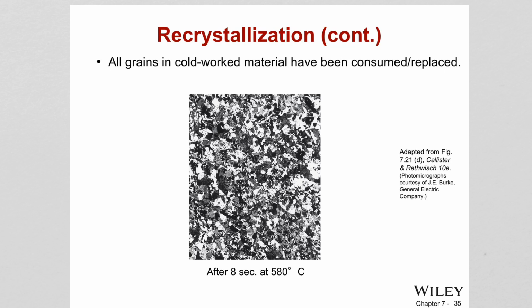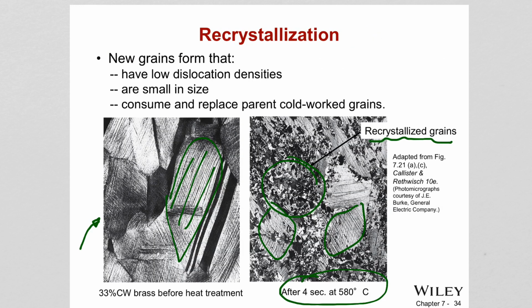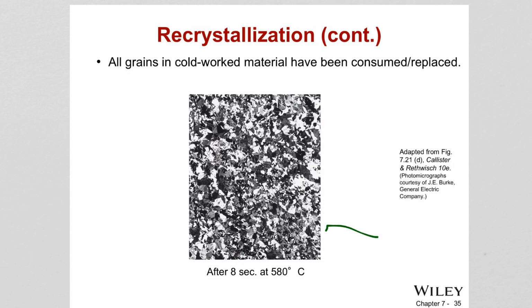Now after 4 seconds, think about just within 4 seconds it was like this, right? And now just add 4 more seconds, within 8 seconds at that temperature, you see microscopically all grains are now replaced. Basically the damaged grains are gone and now we have new fresh, small grains.